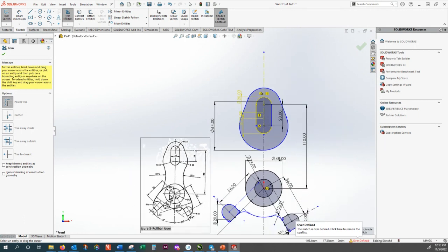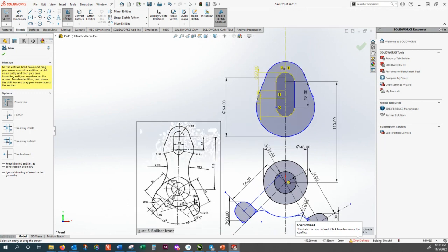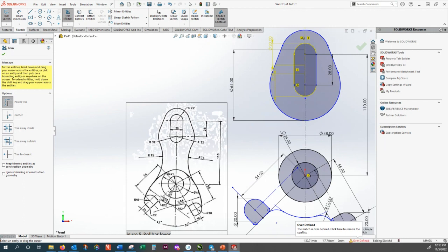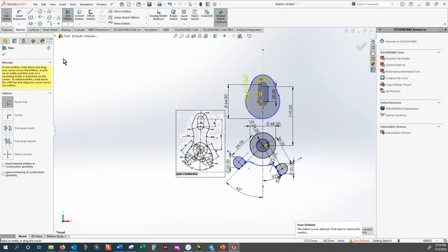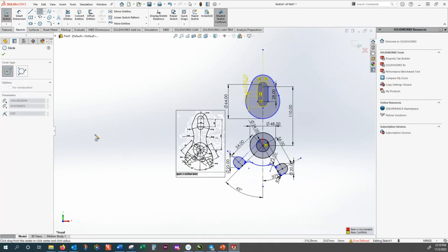So the next thing we do is, all right. So let's have a look at radius of 88. Radius of 88. We don't know where the center is, and so we want that radius to be maintained and tangent to here, tangent there. Okay, how can this be done? I suggest we do a freehand 88 somewhere.